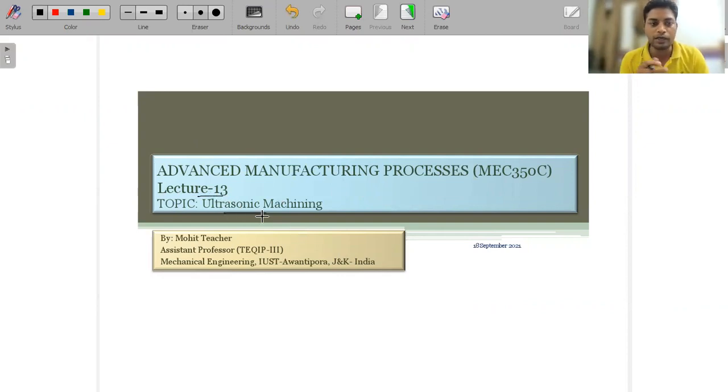But I just want to brief you that in the last three lectures, 10, 11, 12, we discussed abrasive jet machining. Abrasive jet machining is a combination of abrasive particles, or in other terms, the grit, and a jet of air. Jet means a very high velocity, in the range of 150 meters per second to 300 meters per second. Using that combination, we remove the material.